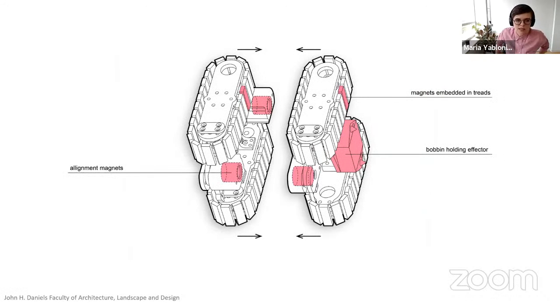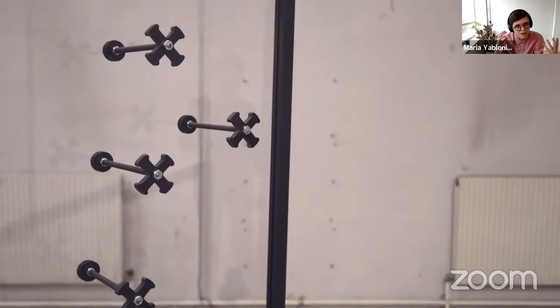So another thing that happened with this project, besides adding another shuttle, is that I developed a new climbing locomotion system that took away all of the vacuum stuff. This locomotion system relied solely on arrays of magnets. It wasn't able to climb on walls; well, it could have climbed on metal walls, but it was designed to climb on relatively thin sheets of material. The project was tested on 5 millimeter thick polycarbonate transparent sheets. But the idea is to think about potentially upgrading the system to operate on materials like facade panels, or even the glass panels of a window. Sheet materials are pretty common in any architectural space, so this extends not only the taxonomy of robots, but also the taxonomy of different environments where these custom machines can be deployed.